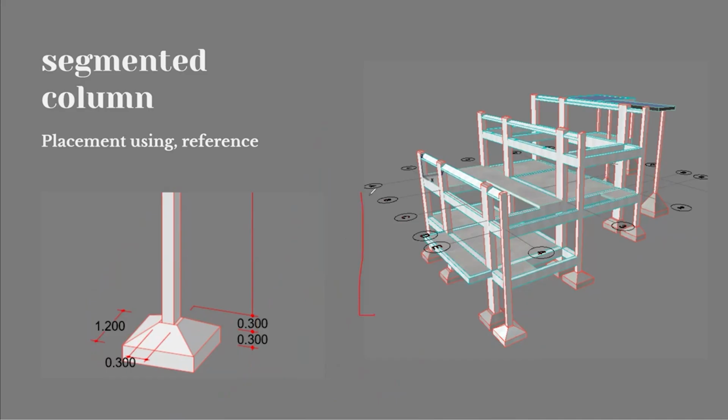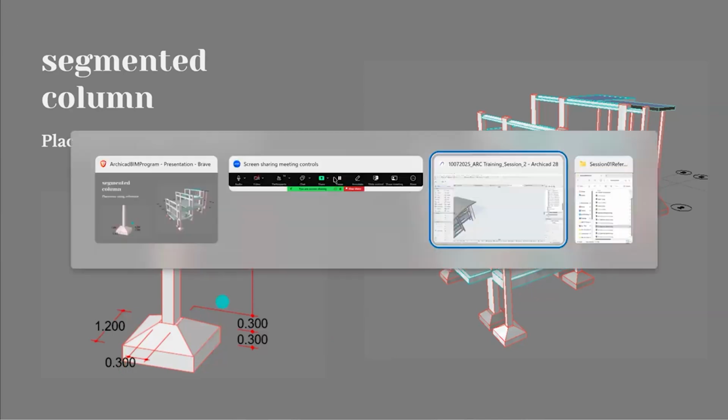So the very normal part, what we have done, is that rectangular column itself. Below that, we have this tapering column that is around 1200 on this side, and then whatever the maximum size is that we can maintain it. And below, we have the third segment, that is going to be the typical rectangle with a smaller thickness. And let's get to ARCHICAD.